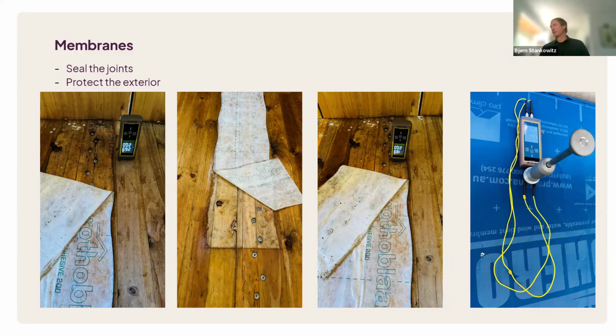And on the other hand, again, look at the blue facade, 14% moisture content. That's behind a facade that's been sitting in the rain. So the evidence is there. It's working. Use it.